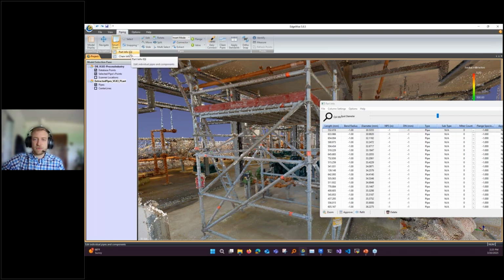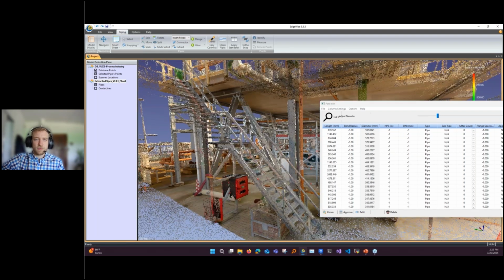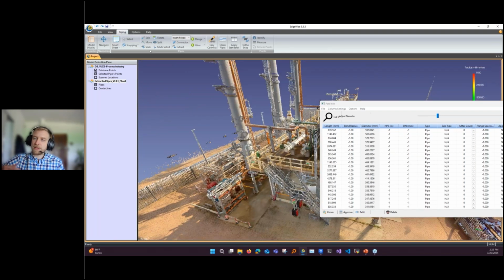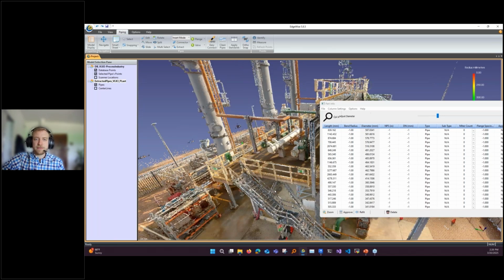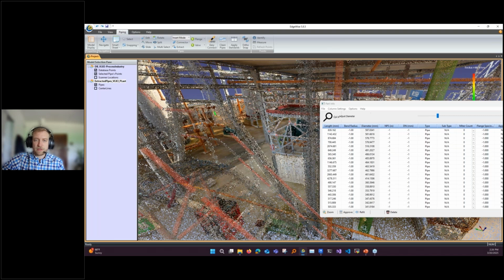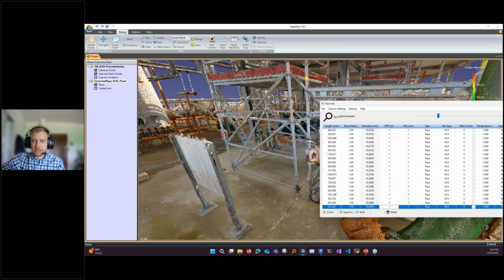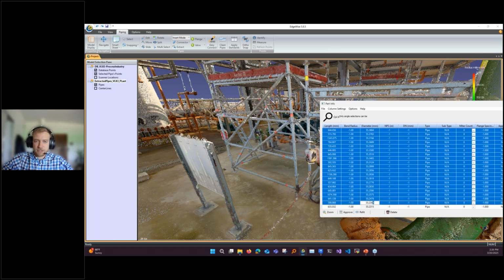And the first thing I'll do is go through and get rid of things with more of a drag and grab type thing and delete groups of things. Or in this case, especially for the scaffolding, I'm going to use diameter, right? So if I click on an element here, I see a lot of stuff that's all 55 millimeters or very close to 55 millimeters, within a couple millimeters. So it's probably a safe bet to say, okay, if I grab this and grab the other direction a little bit, so it's 50, 55, and I do a shift select.